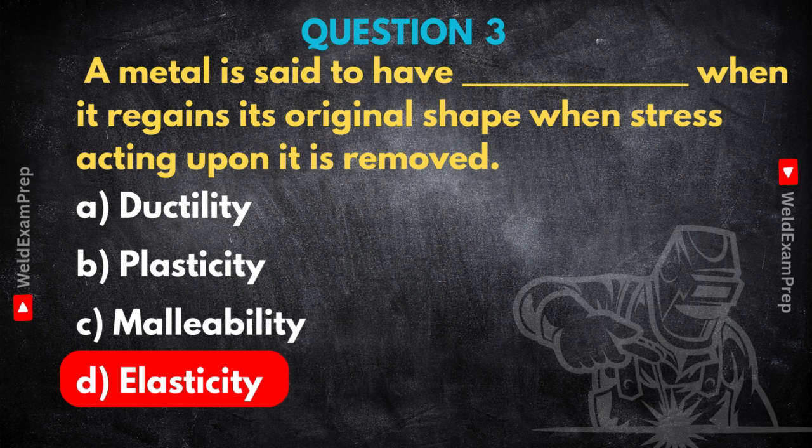You got it. And for an inspector, understanding these is fundamental. Is this component designed to flex under load and return to shape, elastic? Yeah. Or will it permanently deform? Knowing these properties helps you assess if the material is suitable for the job, if the weld will behave as expected under stress, and if it meets the design requirements for safe operation. It dictates how it performs in the real world. Makes sense. It's about predicting performance.